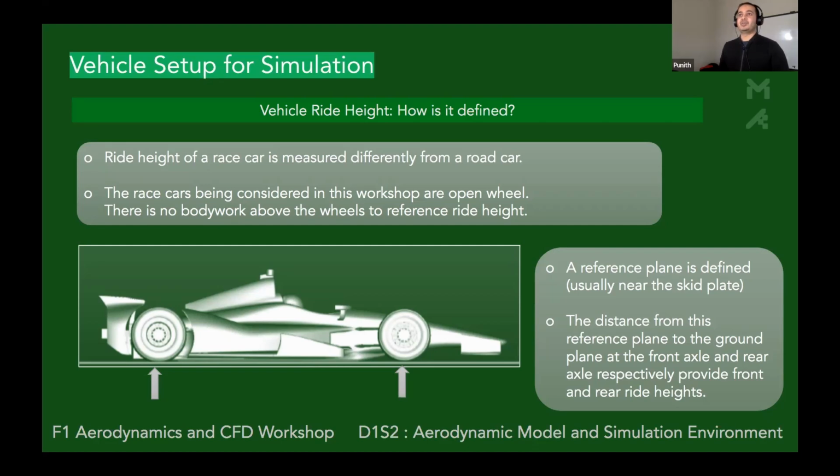because the most important things are cornering conditions for a race car. That's where you want your aero forces to be at their best. And different speeds of corners have different car attitudes. The car is at a different ride height, a different roll, different steering, a wide variety of steering angles, for example, different corner speeds. So it's a huge range of attitudes and positions of the car that you can simulate.